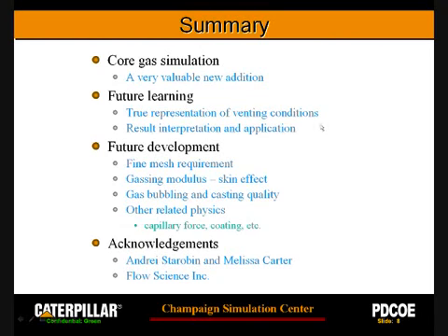There are questions concerning venting, especially the parting lines, and a lot of conditions cannot be very well represented in the geometry model. I think that's something we need to look into to get a better understanding, because a lot of times you receive the model and you don't get the full picture of what's happening in the shop.